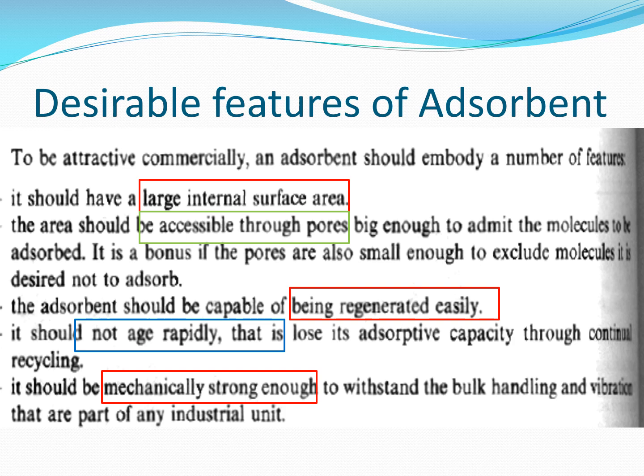So there are certain characteristics of the adsorbents which we require in order to have a better adsorption rate. For example, the adsorbent should have a higher internal surface area, should be porous, and the pores should be easily accessible, like the particle size must be smaller than the pore size, so particles can move through the surface pores and enter and be retained inside the active sites in the pores.